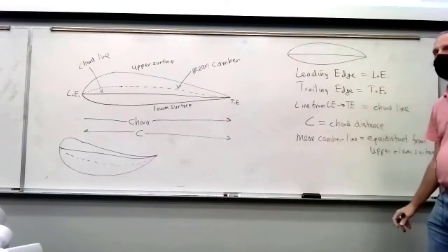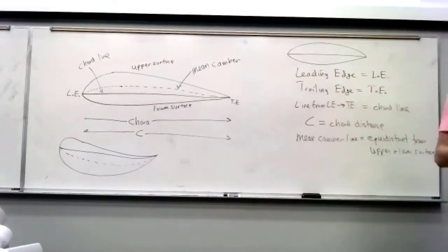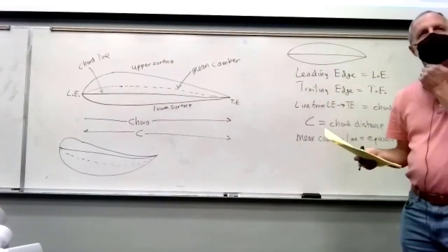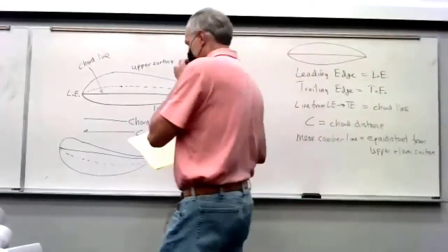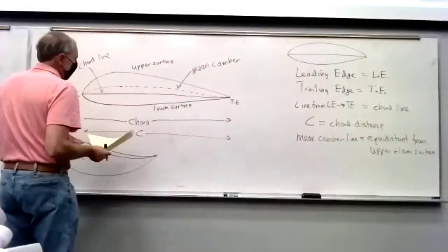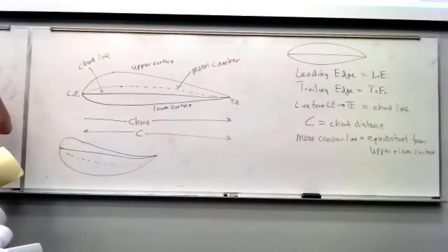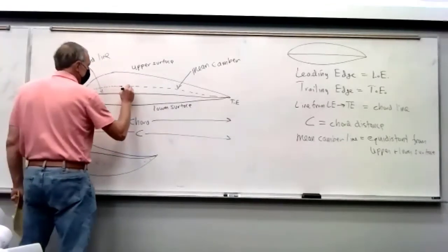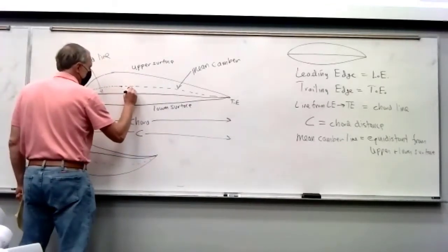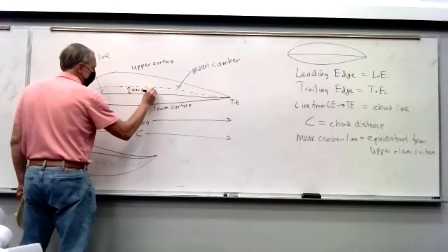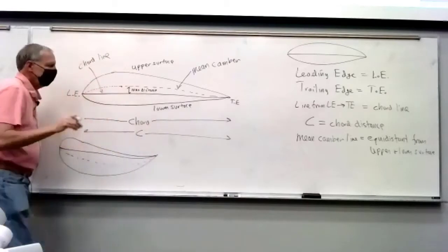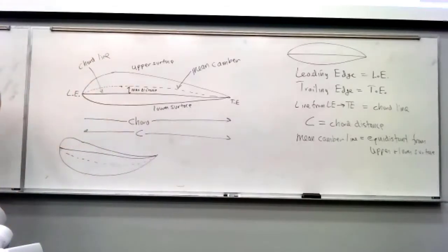And these are standard measures that we make of airfoils that people have standardized and say, okay, I have an airfoil that is 10 foot long and has a camber of 1 inch. And in fact, that's what we'll do, we define the camber as the maximum distance between the chord line and the camber line. You find the maximum, and that tells you how much that's curved upward.